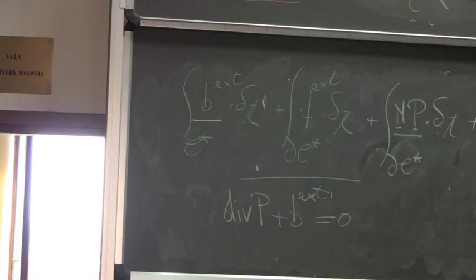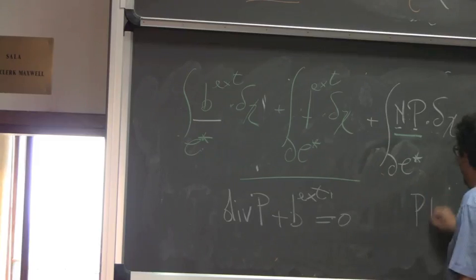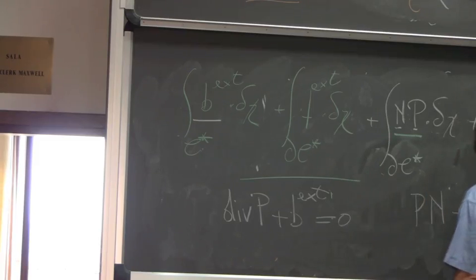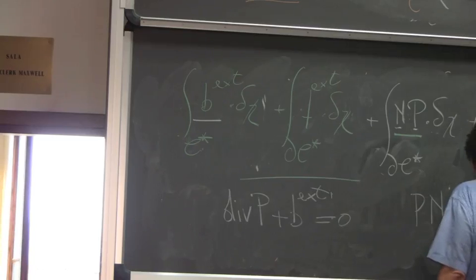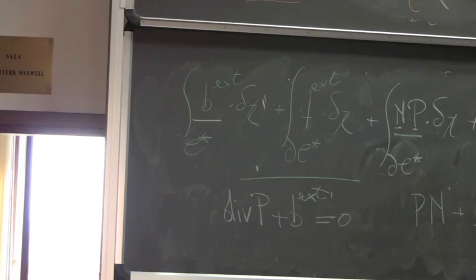Remark, it is written in the reference configuration, not in the Eulerian configuration. You have seen the version of this equation maybe in the Eulerian configuration. Okay? And then we have P n plus f equal 0, which tells you that the force applied per unit surface to your body is equal to the Piola stress contracted with the normal n.